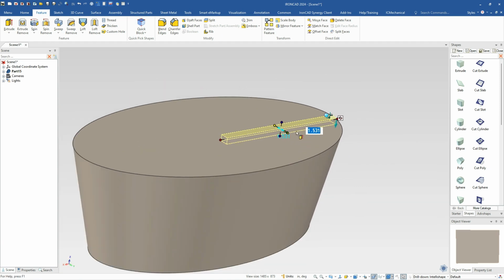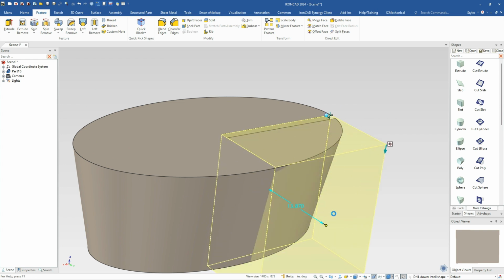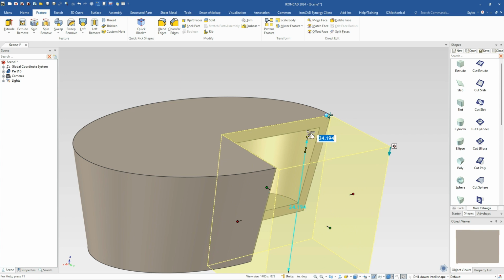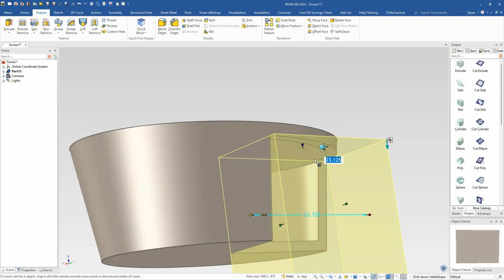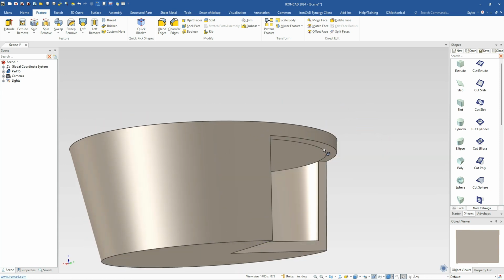Sorry, I'm just going to move my mouse here. What I'm going to do is drag this handle there. I'm going to select this down, grab this handle, and pull it all the way down, and we're going to pull this one out. What we want to do is set this overall height minus 2. So we're going to offset that 2 millimeters, or I could just pull it down and snap to the inside of that shelf. The base, either way, would work.